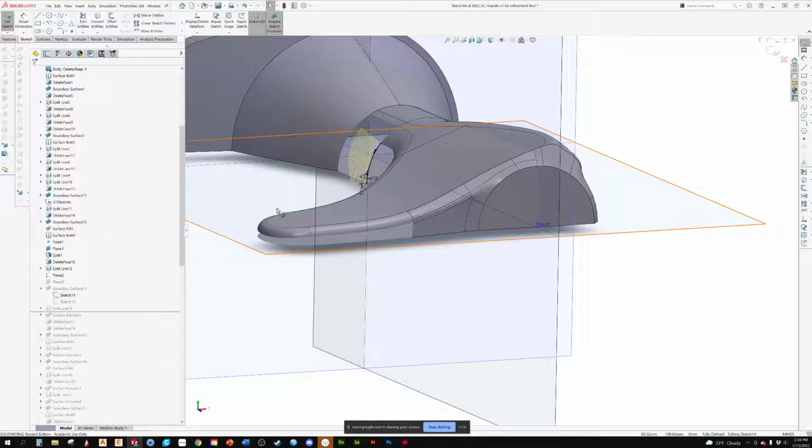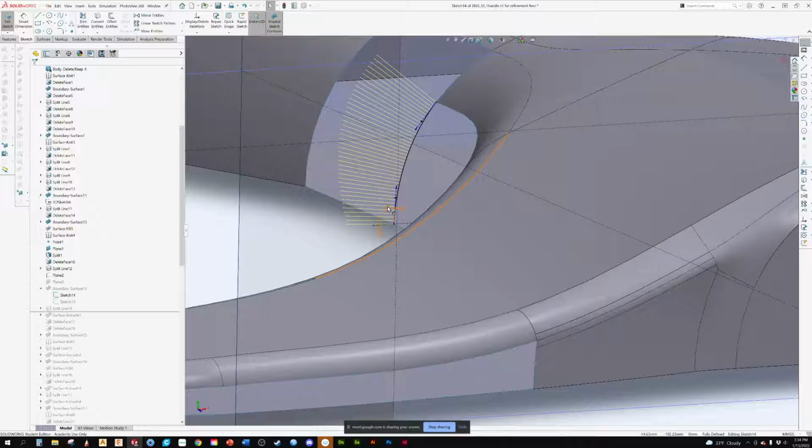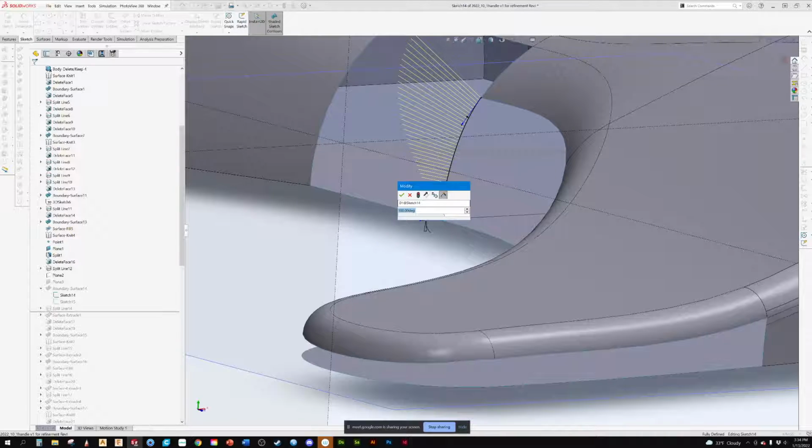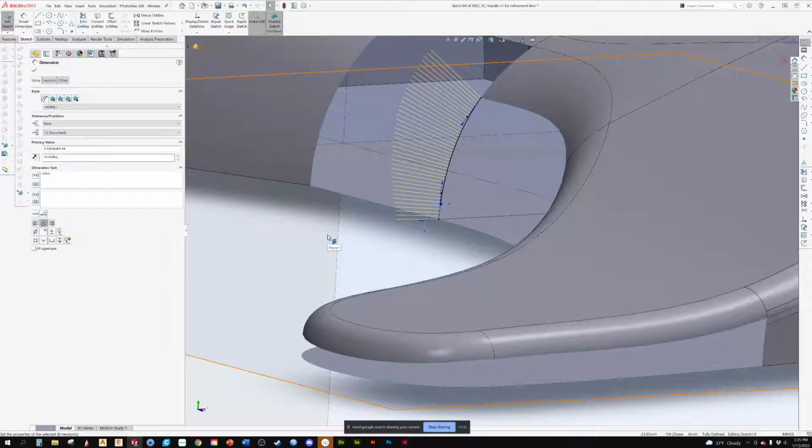So, for example, if I need 10-degree draft on here, you can see how that's going to change that wall. It's not curved anymore. It's almost straight. So that's where you want to be careful, because what happens is by not doing this, someone gets the model and says, well, that's not what it looked like. I loved what it looked like or felt.